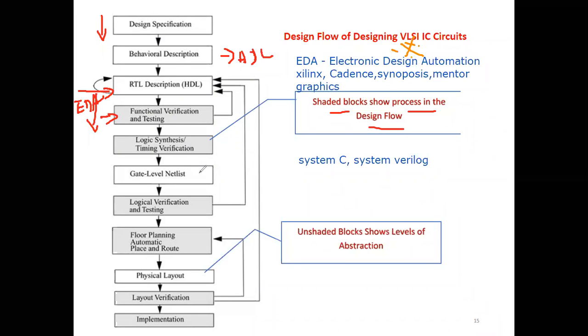That is what I can say gate level netlist. That we can call as synthesis. The synthesis will generate the netlist. That is the meaning of that. So during the synthesis there only we will perform a timing verification. So this logic synthesis will give you how the gates are interconnected. The logic synthesis tool will ensure that the gate level netlist meets timing, area and power.